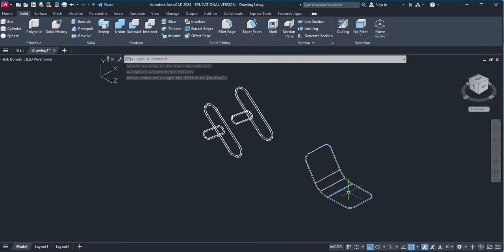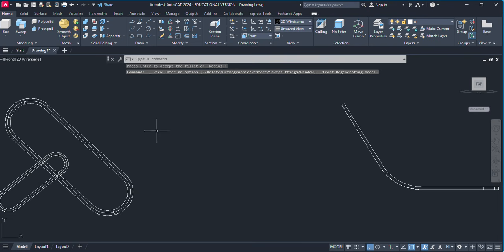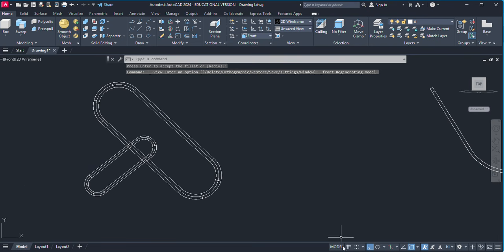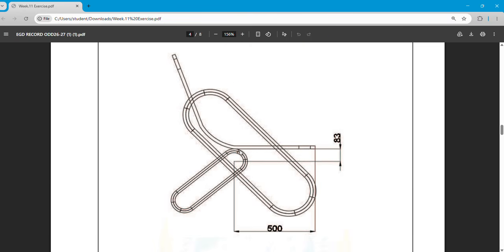Now this can be placed over here. For that placement, you go to front view. See now, where should it be placed? See this point, straight to this center. So from here we have to draw a reference line 500, and first we will place it here and then move it 83 mm.